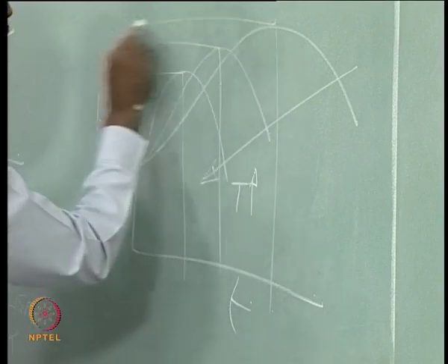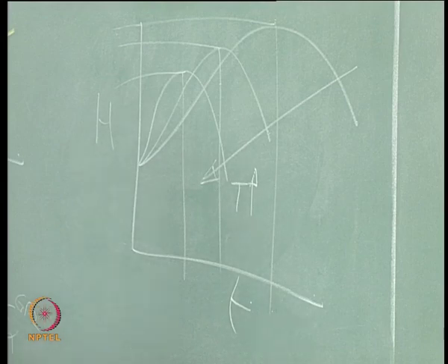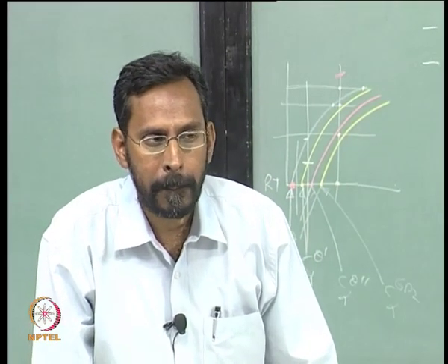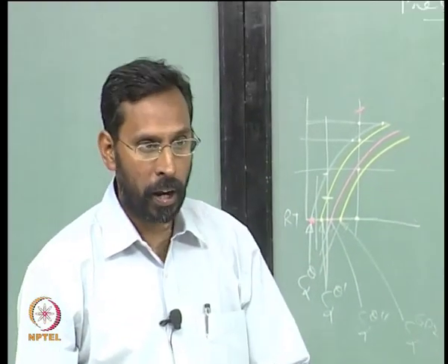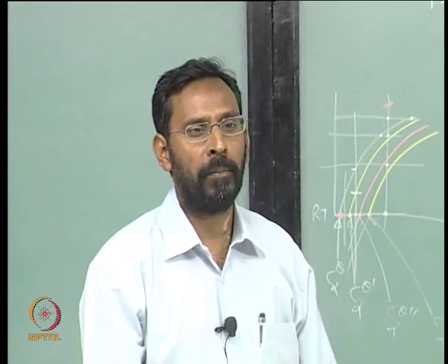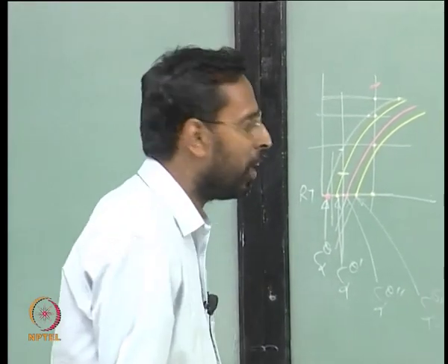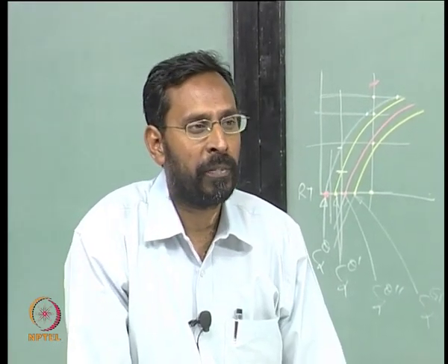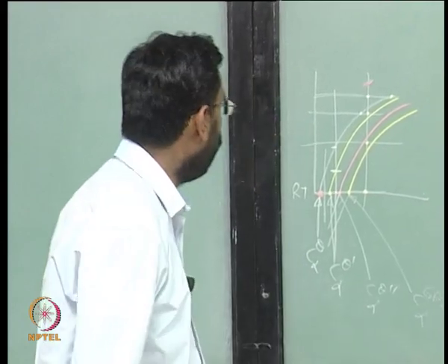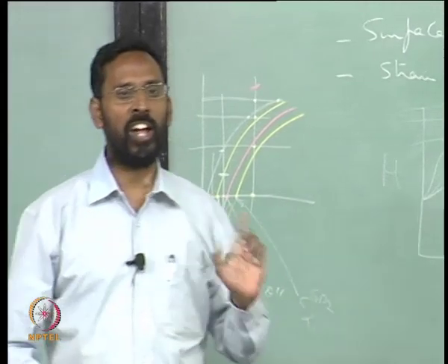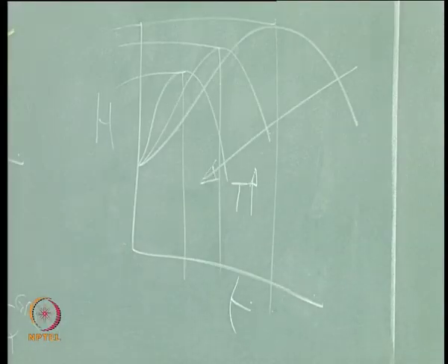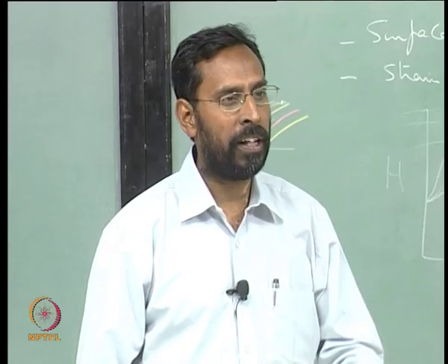Why does the peak hardness come down? Can somebody tell me? Nucleation rate is... Coalescence is one question. Something more fundamental which you can see from the phase diagram. If you look at the phase diagram, ignore all these solvus lines, just think of only one theta solvus and then tell me what would happen if I keep on increasing the temperature.